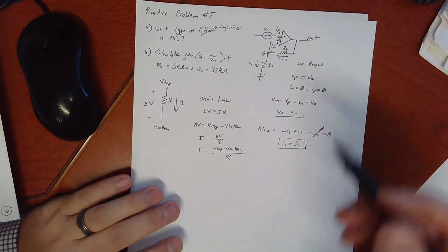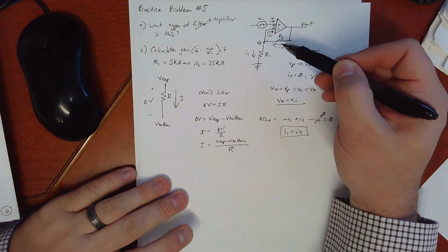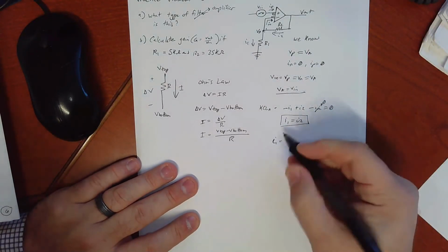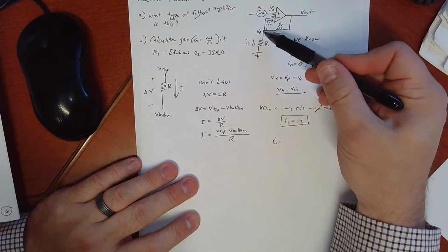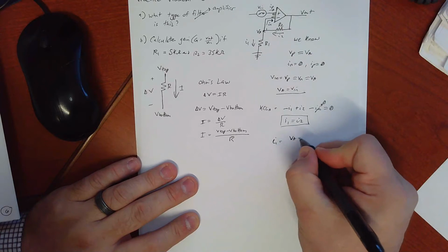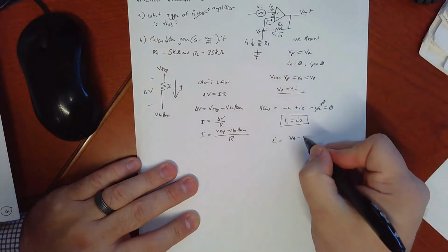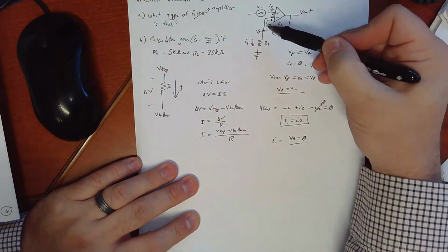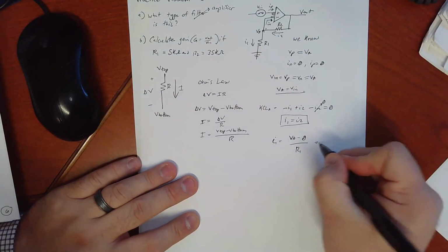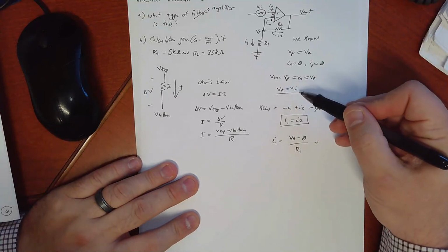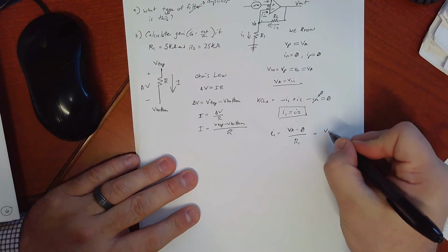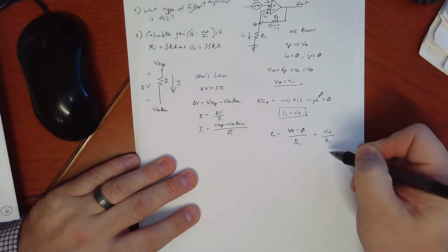Right? And this form becomes very convenient when we work with op amps. So, if we want to reuse Ohm's law here for I1, what do we see? For I1 then, the top is VA, so it's going to be equal to VA minus ground, which is 0, divided by R1, right? And we know that VA is equal to VN. We saw that previously, so we can say that's equal to Vn over R1. So we have a relationship for I1.